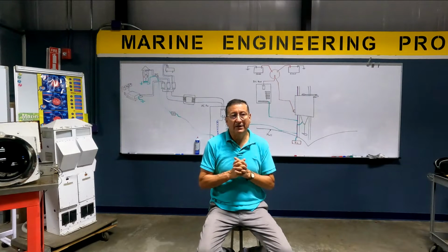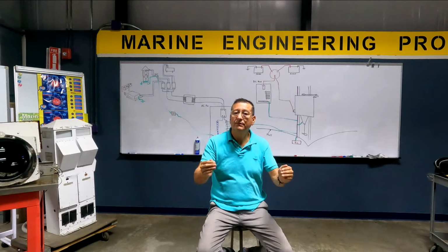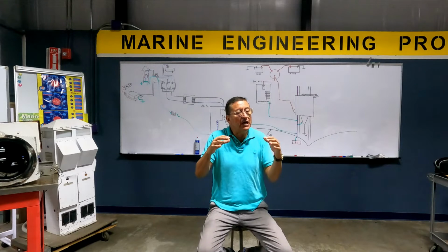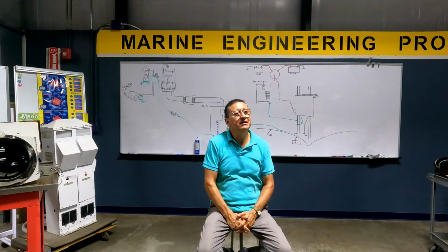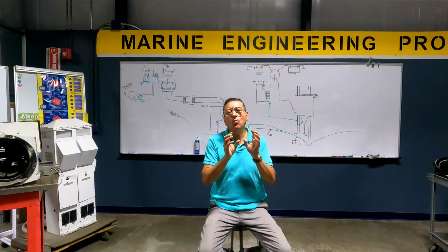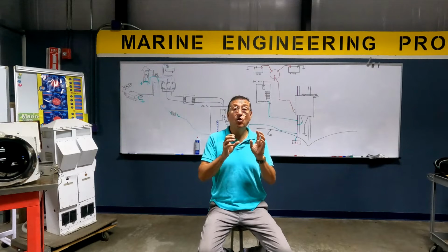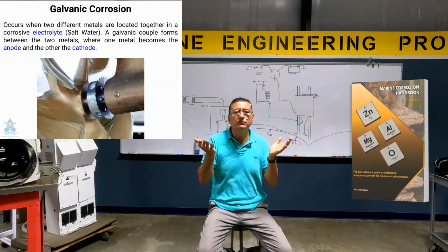Understand that the static electricity should be drained. If not, that accumulated electricity accelerates the corrosion between the dissimilar metals. What is the name of that corrosion when one metal with more energy, more noble, attacks the less noble metal? Galvanic corrosion.